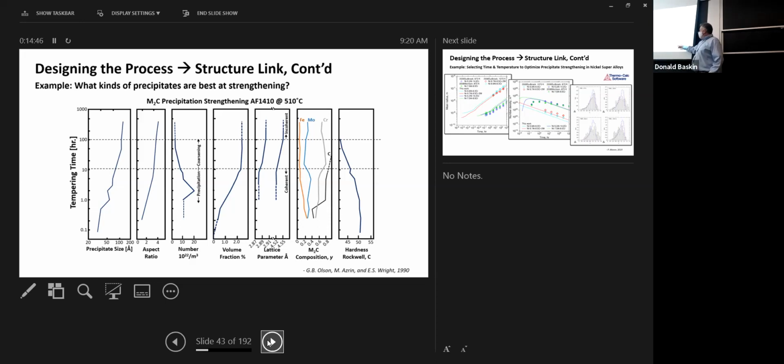Strength. Hardness is a good proxy for strength. Hardness tests give you a good idea what the strength of the material is, and they're really cheap and easy. Doing tensile tests, we actually have to make a dog bone and pull on it, find an Instron machine and calibrate it and make sure that you don't break the load cell, thank you. That's all a pain in the neck, right?